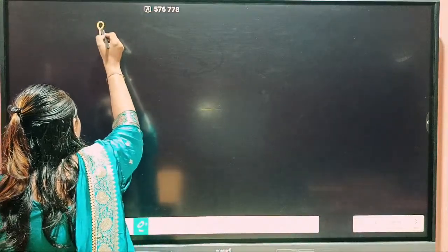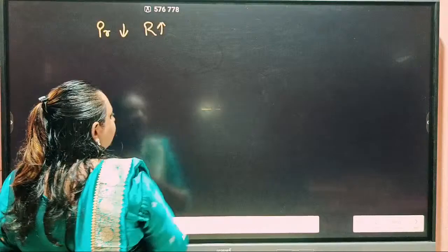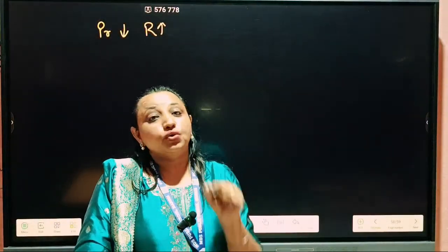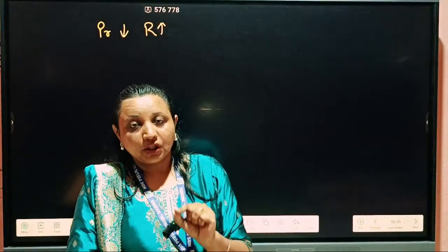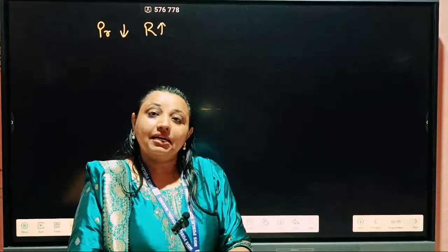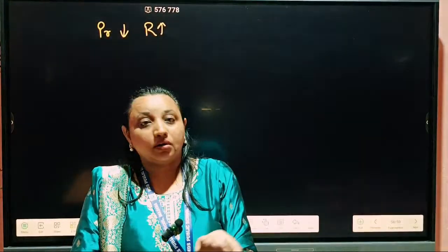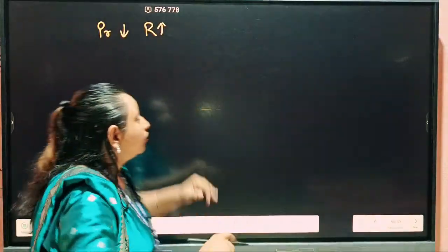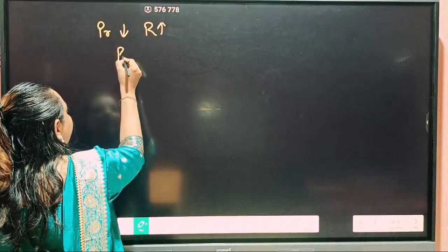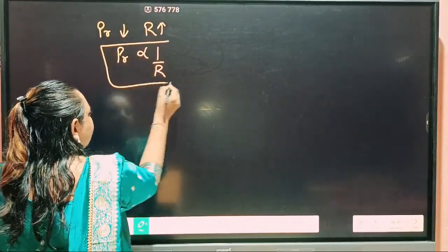If rated power is less, it has higher resistance. अगर 40 वॉट रेटेड पावर थी, उसका रेजिस्टेंस ज्यादा आया, 1210 ओम, लेकिन सेकंड केस में जिसकी रेटेड पावर 100 थी, ज्यादा थी जिस बल्ब की रेटेड पावर, उसका रेजिस्टेंस कम हुआ. तो from that example what we concluded that rated power is inversely proportional to the resistance.